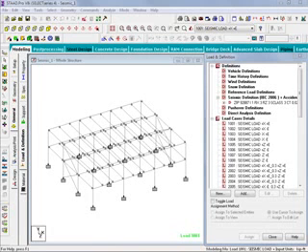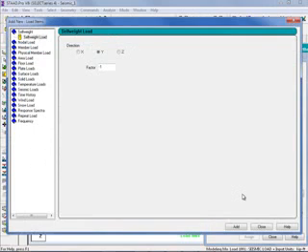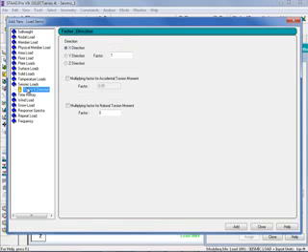To create our first seismic load item, I will go over to the load case details section and highlight my 1001 seismic load case. This load case will represent seismic in the positive X direction with the positive effects of accidental eccentricity. Once I highlight this load case, I will go ahead and click Add. And since I've already created my seismic definition in my previous video, I am ready to populate this with my seismic load item. In the Add New Load Items dialog, I will select the Seismic Loads option.